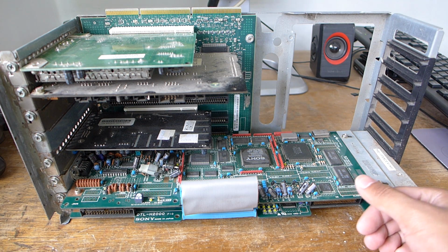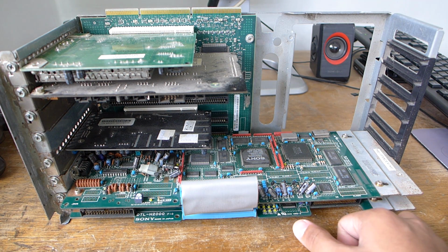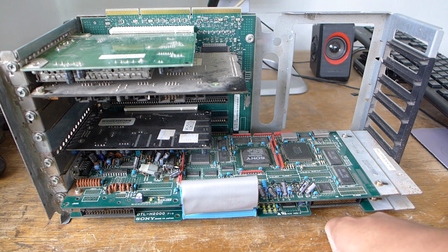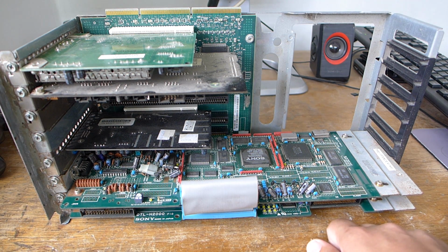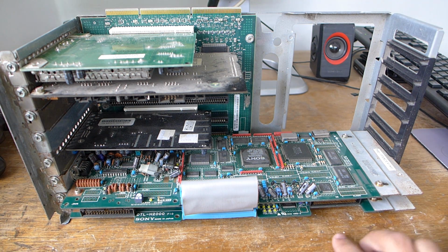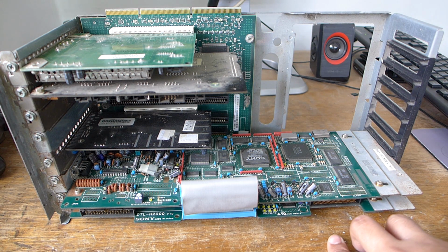So that's the CPU board, and down here is the PIO board, which is responsible for I/O stuff such as the controllers, I/O for the CD-ROM, whether it be a DTL-H2010 or 2510 CD-ROM drive, or the CD-ROM emulator card, which uses a SCSI hard disk as the image to store your ISO on, and also where you connect your DTL-H2700 performance analyzer board.